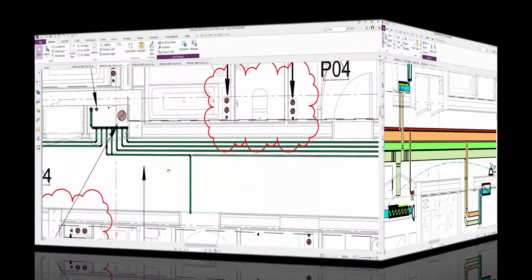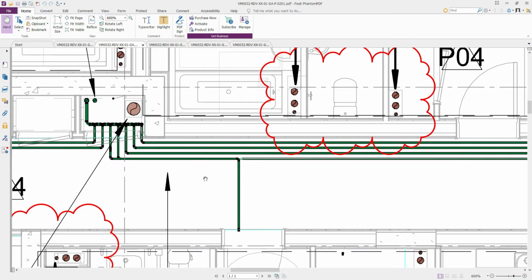I'm gonna start from boosted cold water service, and I can see that I need to model 5 pipes. So I'm gonna choose boosted cold water service from the MEP fabrication parts browser in Revit. Diameter of the pipe is 22 mm and insulation is 40 mm thick.